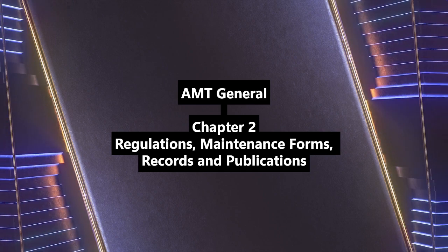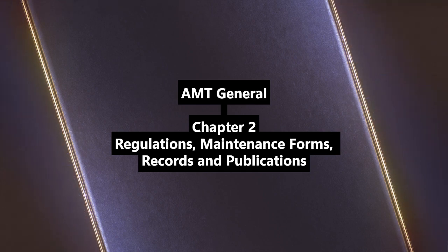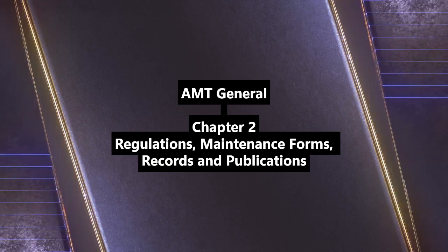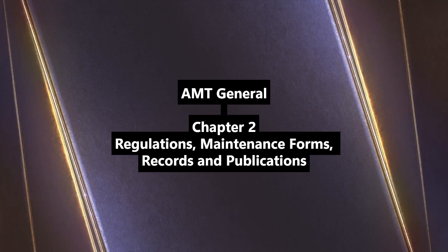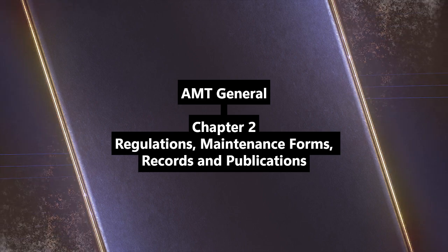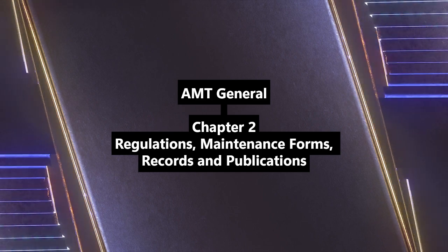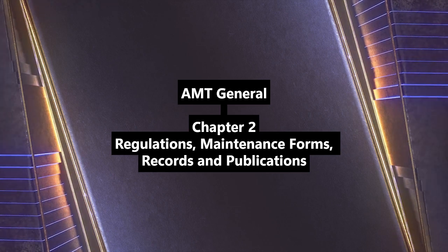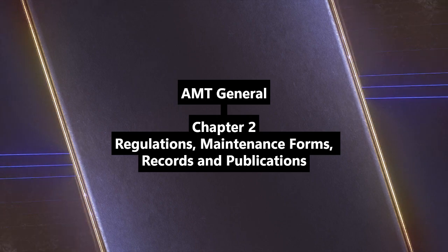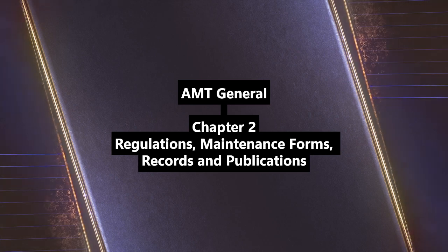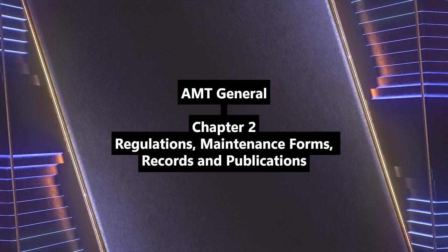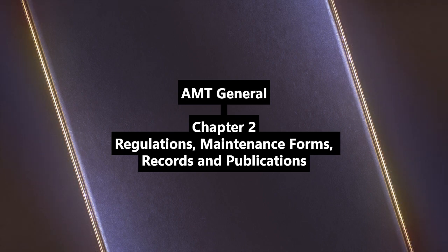Now, what about the operating rules, Part 91? 14 CFR Part 91, General Operating and Flight Rules. Yes, its main focus is flight operations, but it's very relevant for mechanics, too. How so? Give me an example. Well, Section 91.207 covers ELT battery replacement requirements. Section 91.213 deals with inoperative instruments and equipment, including minimum equipment lists, MELs. Things a mechanic would definitely be involved with. Absolutely. And crucially, Subpart E of Part 91 is dedicated entirely to maintenance, preventive maintenance, and alterations. Ah, so a direct link back to maintenance standards. Yes, it constantly refers back to Part 43 for the how-to.